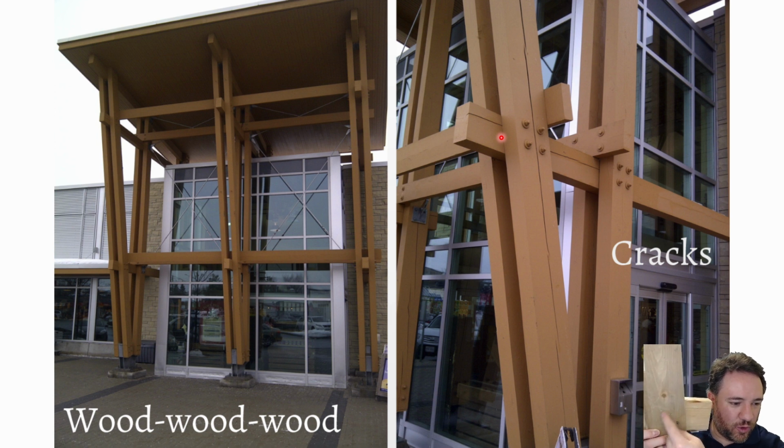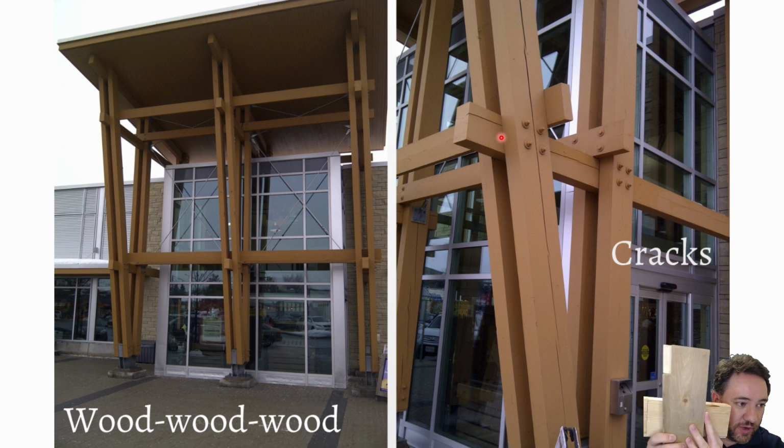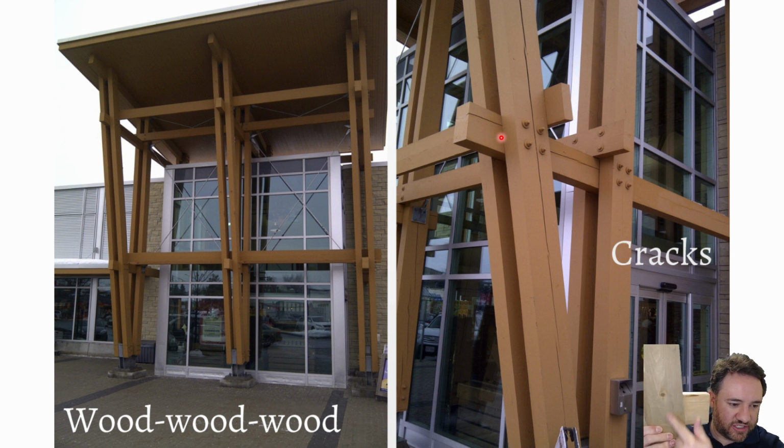The bolt holes themselves can accommodate a little bit of that, but only up to a certain point, right? So here, these are pretty big members. We have 2 bolts like this, and as the front member wants to shrink in this direction, the back member does not allow the bolts to move in that direction, which means the bolts stay in place and the member shrinks between them, which creates a tension stress, which causes a crack.